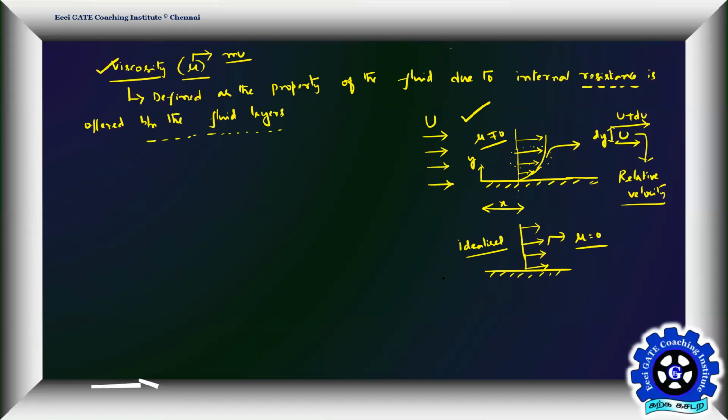So that's why these kinds of problems come under inviscid, that means you are not including viscosity. That's why this is inviscid fluid dynamics, whereas this is viscous fluid dynamics. Are you guys able to catch that point? That's why the chapter was divided into two parts. One is inviscid fluid dynamics, where you neglect the viscous effects and assume the velocity is the same everywhere with respect to y. Whereas the problem in reality will be the first one, where I have given a tick mark, where you see velocity changes with y because of the property called viscosity.